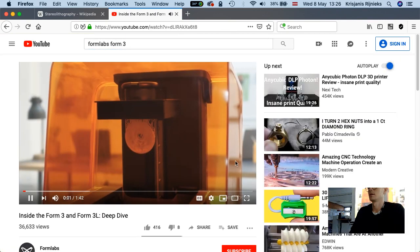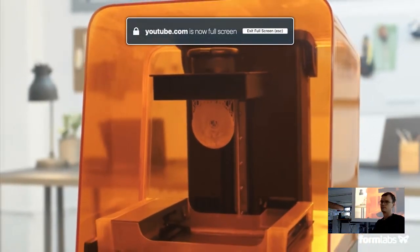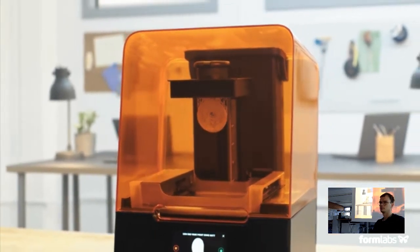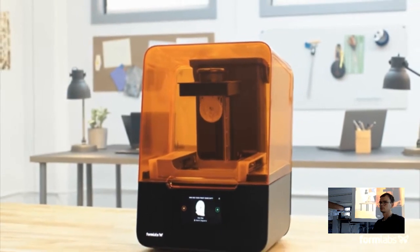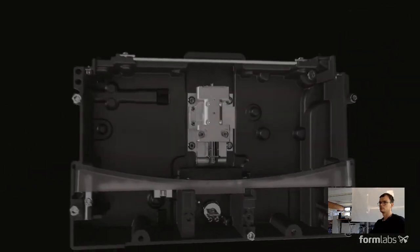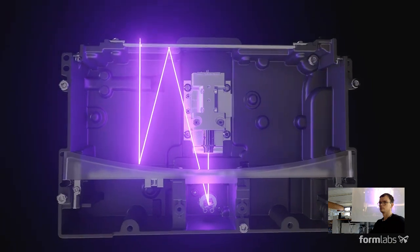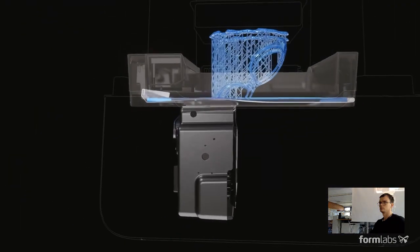The Form 3 and Form 3L are powered by low-force stereolithography. This advanced print process adapts your part's geometry to consistently deliver flawless prints. At the heart of the machine is the Light Processing Unit, or LPU, an enclosed laser system that uses spatial filtering and a parabolic mirror for uniform illumination across the build area.